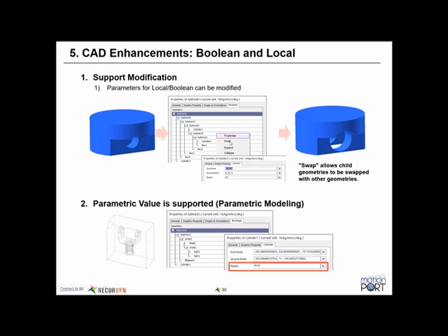So that's been available for some time, but what used to be the case is that, in the case where you're creating your own geometry, you would have a collection of primitives and a collection of Boolean operations. Once you had that built up, if you wanted to make a change, you had to delete and undo a lot of things, make the change, and then redo the Boolean operations. But now we have this ability where you can actually go in and change the properties. You can see on this pop-up menu, there's a properties capability on this tree, which has now been added.